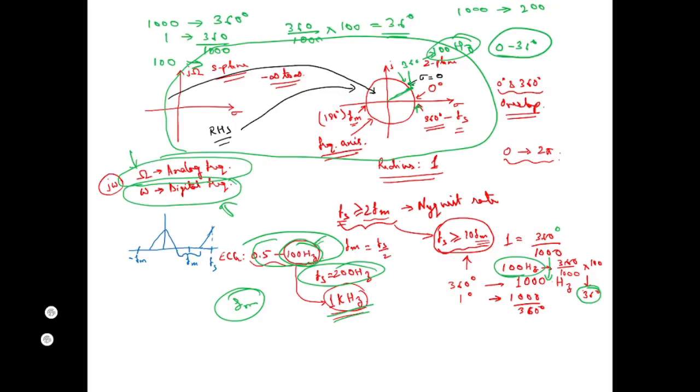The thing is that over there, we cut every alternate point, so it was a decimation by 2. Here, what should my decimation be? By a factor of 5. If you do it, you will be able to reduce the number of data points per second from 1000 to 200. So now, are you able to appreciate what you studied previously?